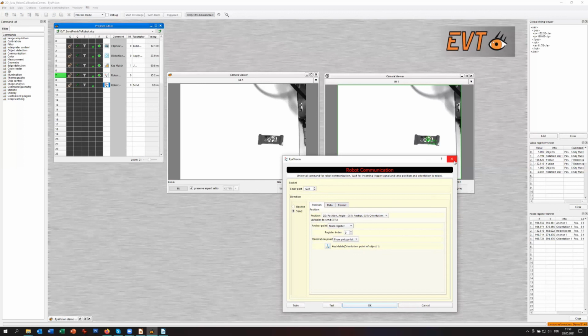But at the end, because the runtime is not so bad, you see it's 23 milliseconds, even on this PC, and this is not the fastest one, it's a somewhat old laptop. You should do this in any case to have a flat coordinate system, which fits the flatness of the coordinate system of the robot. So I hope this answers your question.